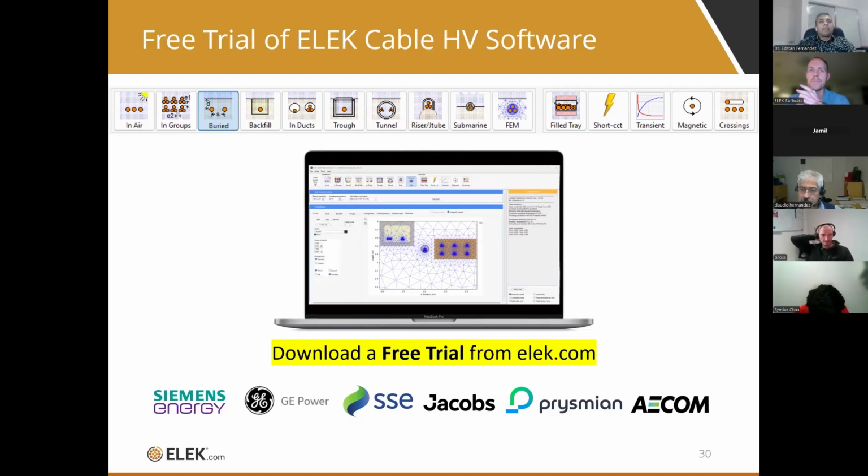The other question is, can we consider other trefoils in the vicinity of other multiple circuits? Can this be done analytically, or do we need FEM for it? It's fine if you don't have casings or pipes. You can use IEC for mutual heating. But when you have HDDs next to HDDs, you have to use FEM definitely.